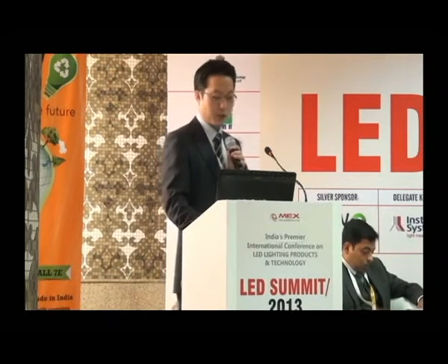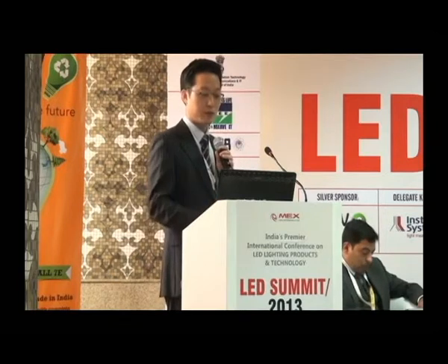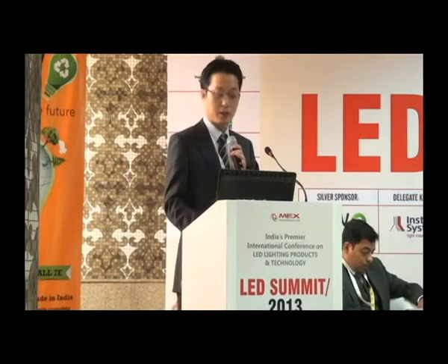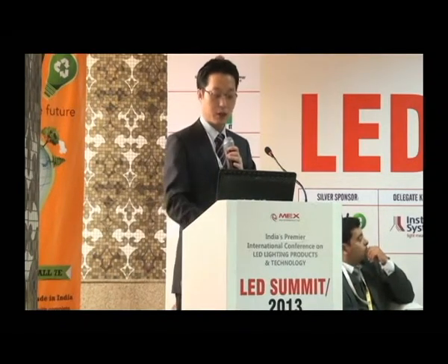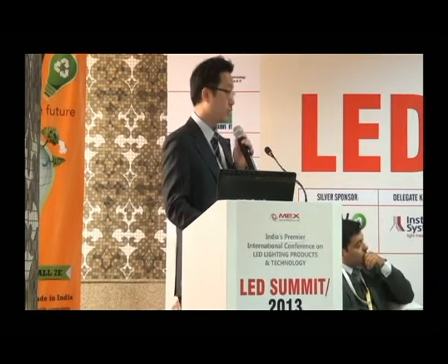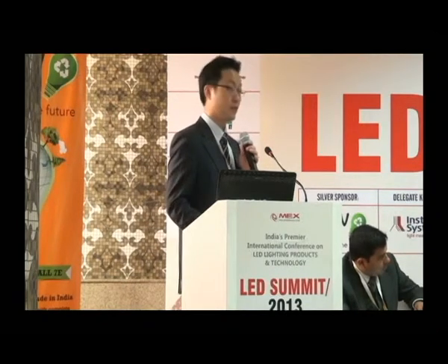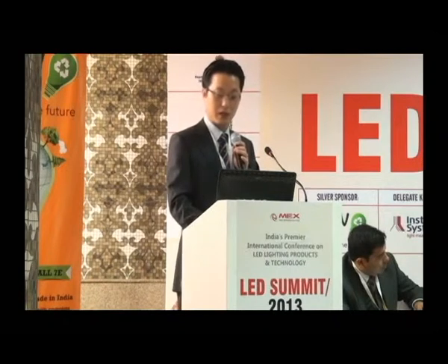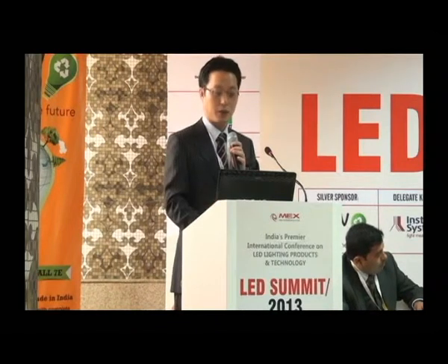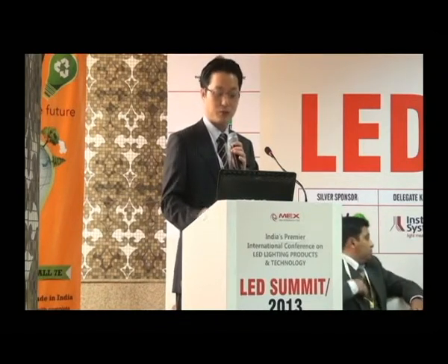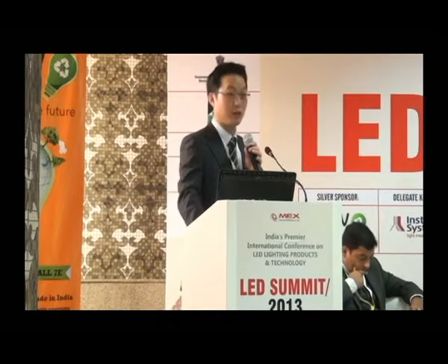Okay, this is the silicone manufacturing process. From sand, we extract silicone metal, and then it is synthesized to chlorosilane, and then polymerized. After that, all together, we make the silicone mixture for LED application. Everything is produced in clean conditions because the defect ratio on the customer side is very important. Sometimes, if customers can decrease the defect ratio, they are willing to pay more to get the pure silicone, because the defect ratio is the main factor that increases LED cost.